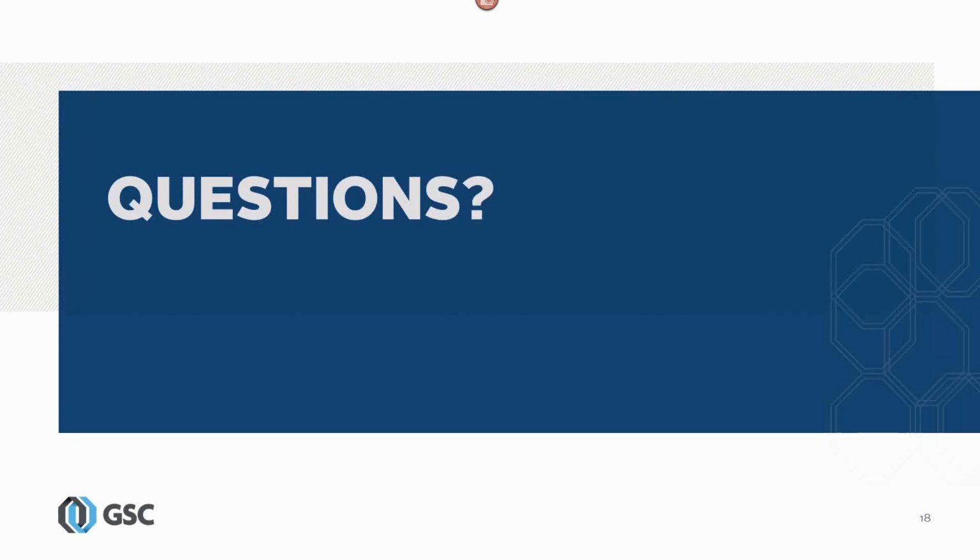Second question says that I am an Altium user for 20 plus years. I want to be able to see the top and bottom copper layers as well as the solder mask openings in the SolidWorks environment. Critical for preventing shorts to housing as well as quantify physical connections to components such as board-mounted coin cell holders. Yep, and that would be something that you would export out as a Parasolid then if you needed to have that copper and that information with it, and that's available through SolidWorks PCB.